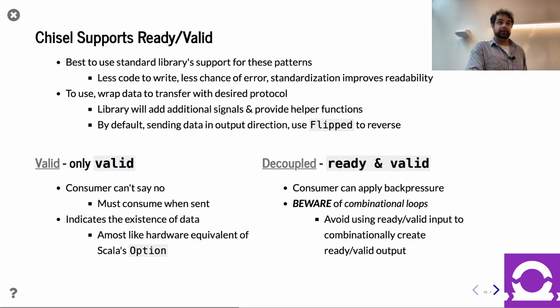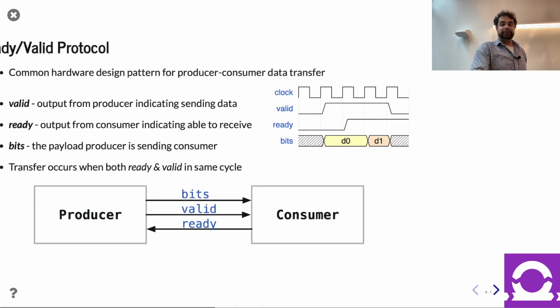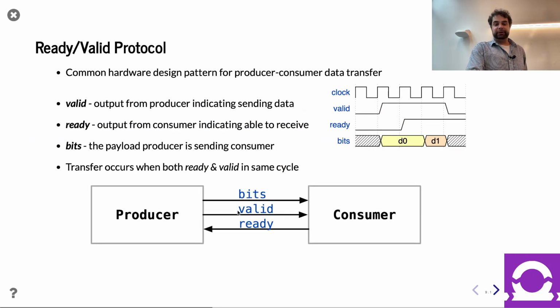Yes, you can stick a flip-flop in there, all sorts of things you can do. Like I said, the common thing that comes up is that if you can generate valid in some manner, it's not that you can't depend on ready. It's just that you can't have a combinational path from ready to valid. And if there is a combinational path from ready to valid, there should also be a combinational path from valid to ready, right? But yeah, if you can produce valid from some flops or internal state that does not directly combinationally touch ready, you're fine.